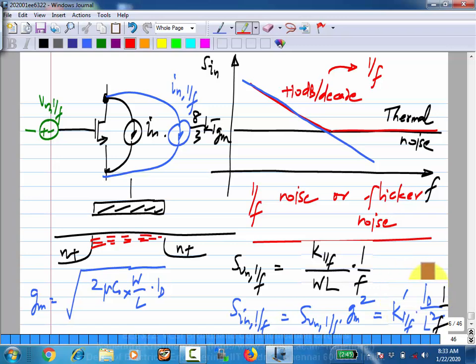This is relevant when, let's say, you are realizing a current source. This means that the MOS transistor will have noise. If you make a MOS current source, like in a current mirror and so on, it will also have noise, and it will have flicker noise. Now what this expression is saying is, let's say you want a less noisy current source, what do you have to do?